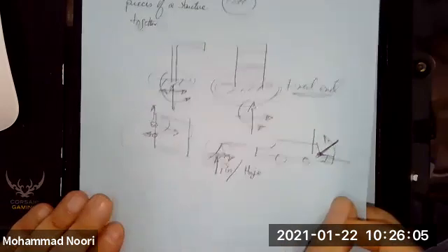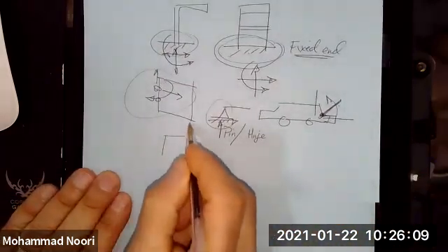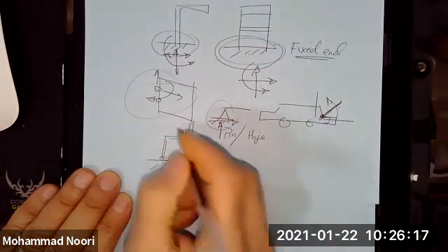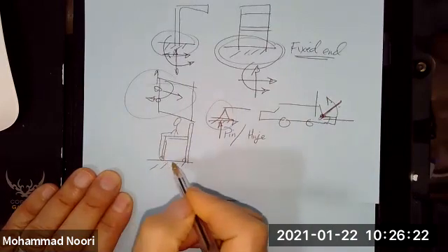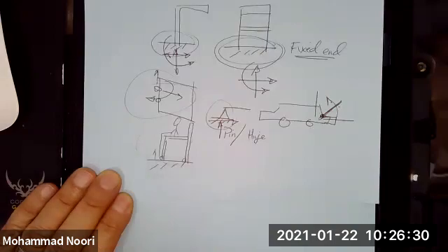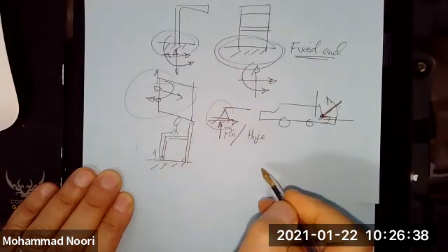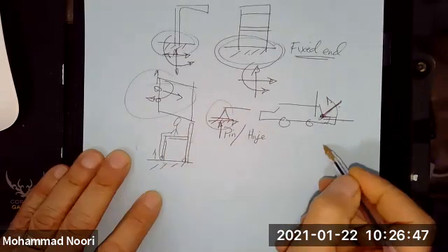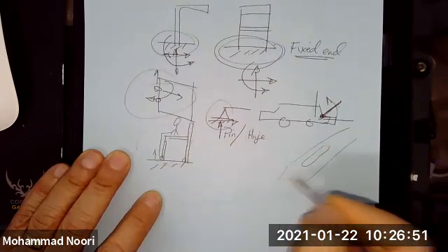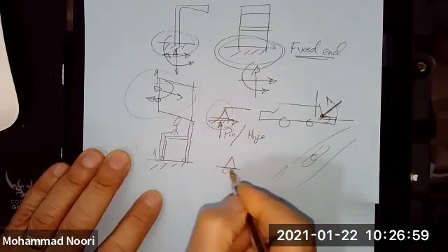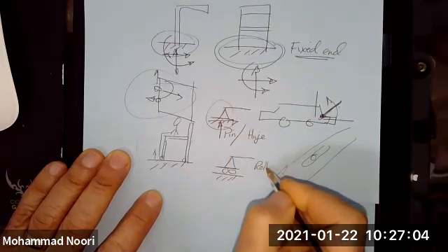There are sometimes cases where you have a support like your chair, especially if you have some rollers here, that you're sitting on. You can lift your chair; there is no force resisting it. You can rotate this, right? But if you want to push it into the floor, you can't. Sometimes you have situations where you have a slot and a bar that can move back and forth and rotate in that slot. We call this support a roller, and we represent it this way.